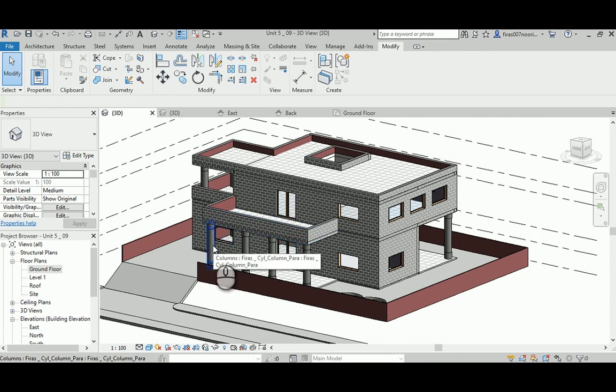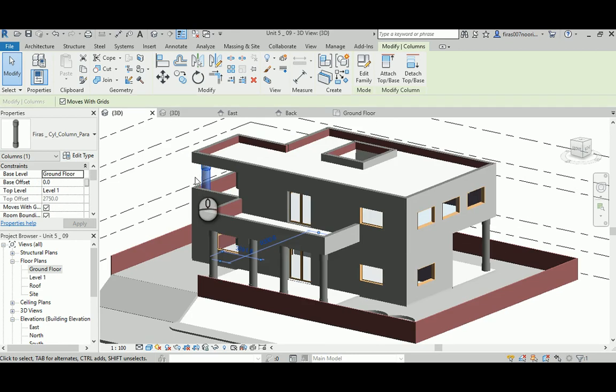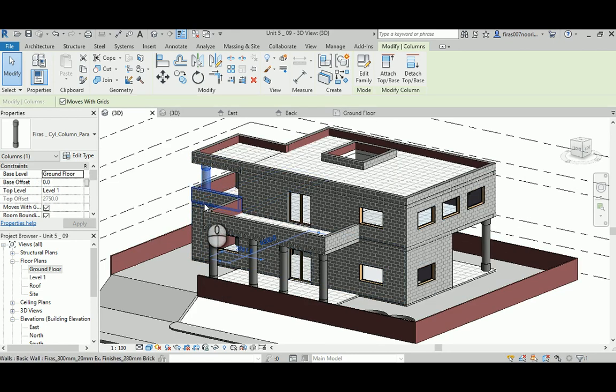In this case, those guys all on the ground floor will have the same height. And I just rather show you, like an example, it could even be penetrating the slab, which is technically wrong. So you should stop it here and then copy it vertically and make the height between the first floor and the second floor or whatever, or the roof.